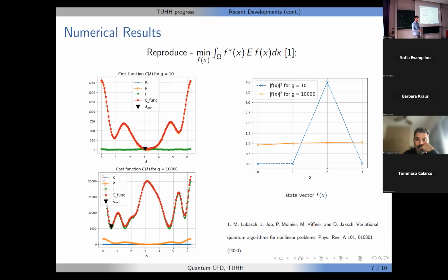So if we now use the particle swarm or a Monte Carlo, we just shoot in a discrete way at various locations and then select the best location. With high probability, we will have a good initial point in order to start a gradient-based method and then come up with the right result. In this way, we are now able to pick directly the optimal point just by pointing at it and evaluating the circuit we have there.